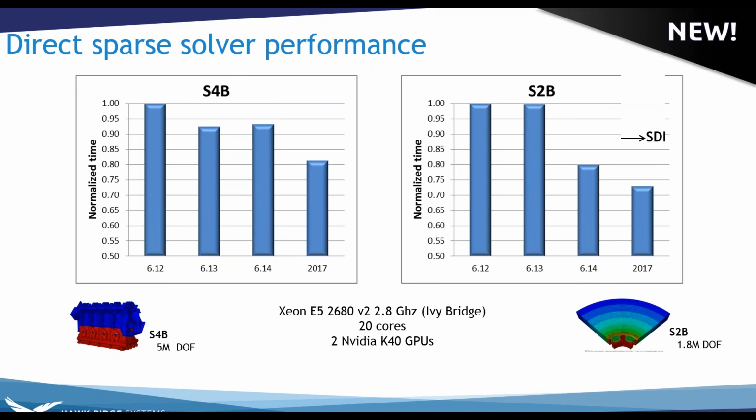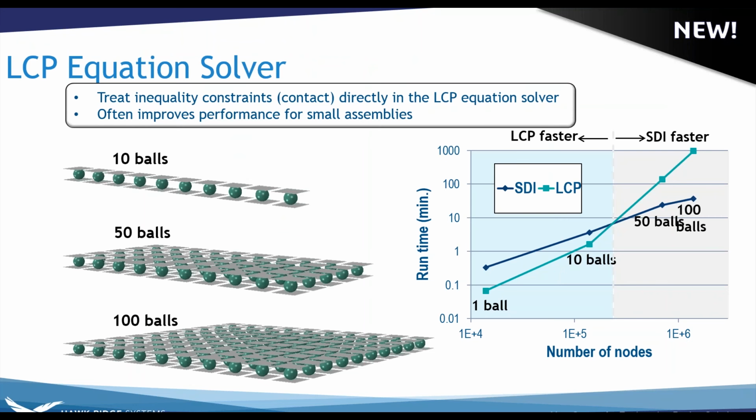The type of problem this would be useful for is something like a bearing set where you have around 10 contacts and you want to do linear load perturbations. You can solve for your material nonlinearity in a base case, and you can do other steps around this in a linear perturbation. So you take advantage of having built the main stiffness matrix and solving some quick steps around it.